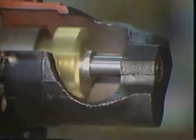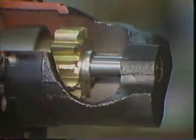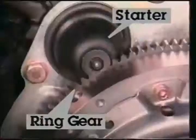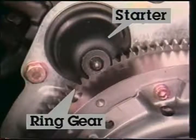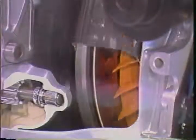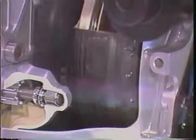The teeth on the pinion gear slide into and mesh with the teeth on the ring gear bolted to the engine crankshaft. Since the ring gear has a large number of teeth and the starter gear has only a few teeth, the motor has enough torque to crank the engine until it starts and runs on its own power. When the engine starts, the driver releases the ignition key so that the pinion gear can retract away from the spinning flywheel ring gear. The one-way clutch keeps the ring gear from turning the motor armature and causing starting motor damage.